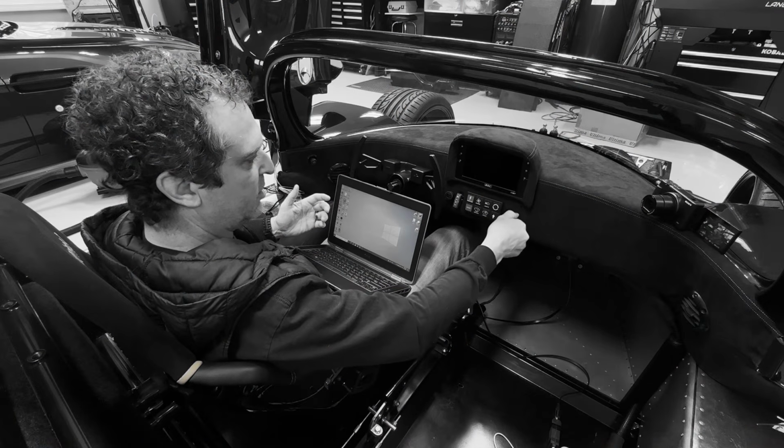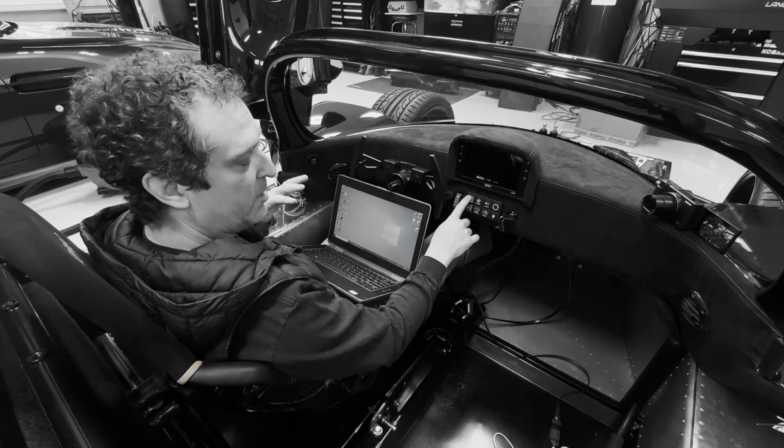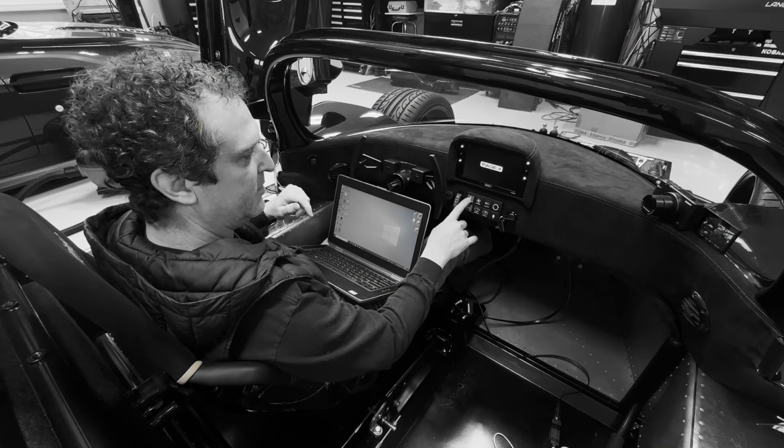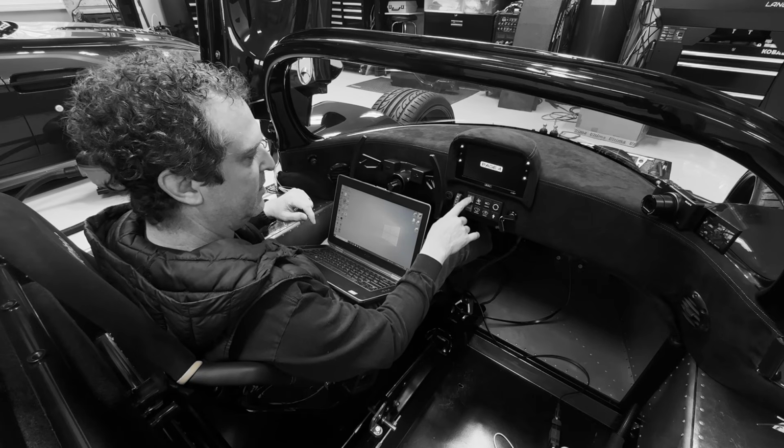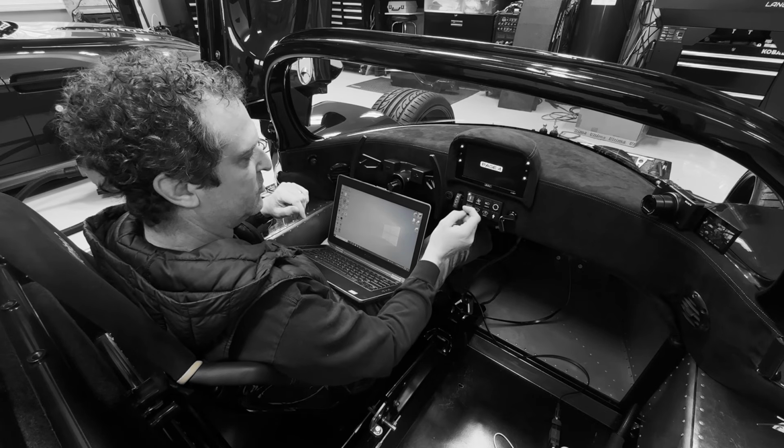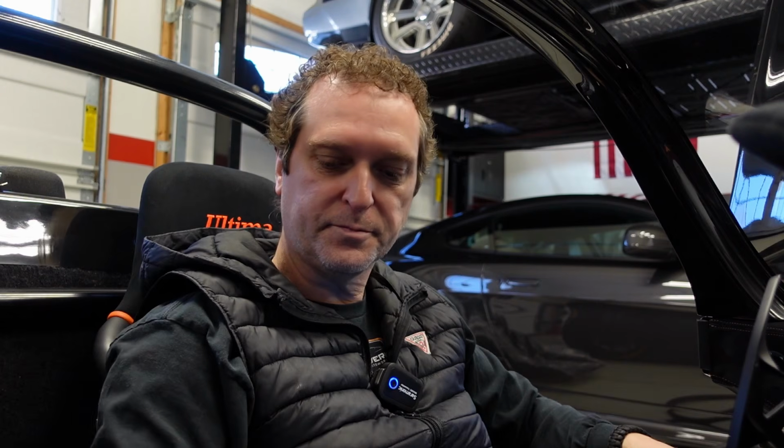All right, the first thing we got to do is connect our CL1000 to the CAN bus and get some live data streaming here. So what I'm going to do first is we're just going to turn the ignition on. I'm not going to start the engine. That's the key. We want to minimize the amount of CAN bus traffic, so let's not start anything we don't have to, but just the basics to get the CAN data streaming, and we could do that with just the ignition. So I'm just going to turn the ignition on here.